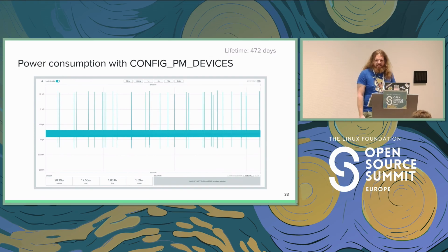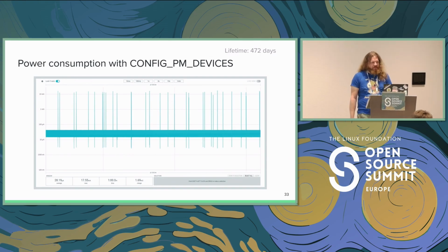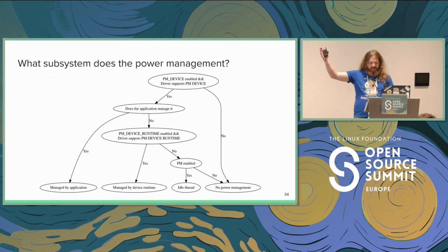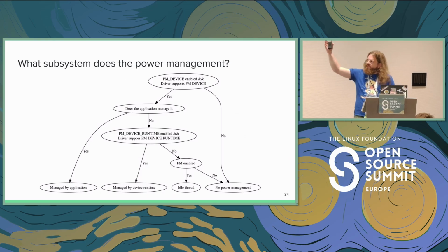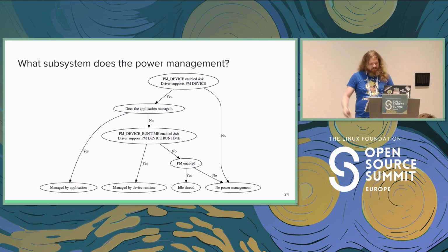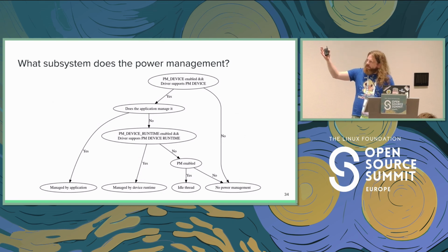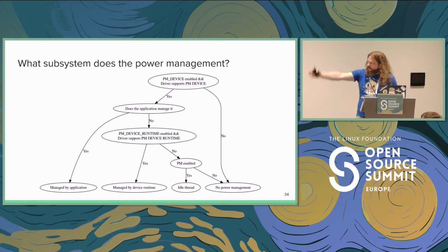I've done it and nothing happened. Why did nothing happen? I mean, we've got PM device enabled and the driver supports PM device, yes. Does the application manage it? No. PM device runtime enabled and driver supports PM runtime? Yes, managed by device runtime. PM enabled? Yes, idle thread.